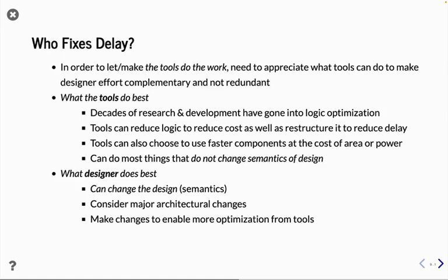So remember maybe in 220 we talked about out-of-order processors and the shift from data in the ROB to a unified physical register file design, right? It's a big architectural change, right? And so you have to kind of, as a designer, recognize opportunity for that and do that, right? And so if you make these big changes, then the tools micro-optimize, right? Now, maybe 30 years ago, you spent a lot of time actually looking at every single logic gate and reconsidering each logic gate. Like I said, in 2023, the tools can do that. Usually, if there's a path the tools can't optimize, it's because you need to architecturally change it. Or you need to decide, you know what, this is too much logic between these two registers, and you figure out a way to break it up or something.